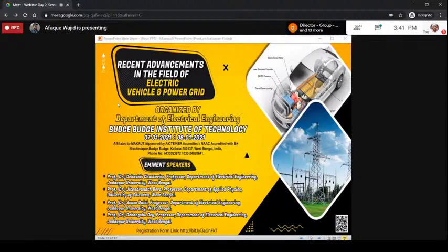But the point is that, for that particular effect, you know that voltage and other things have some tolerances. Even if you have some deviation, the loss and other parameters will vary, but it will not entirely make the transformer go out of service. So that is why the importance is much more. Before degradation of that level for the core, the insulation may get damaged. So first importance is usually given to the insulation condition, not to the core.